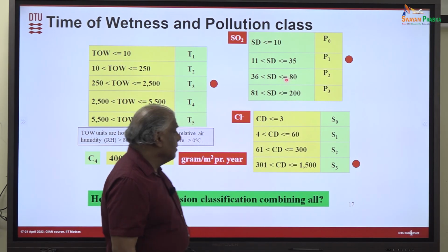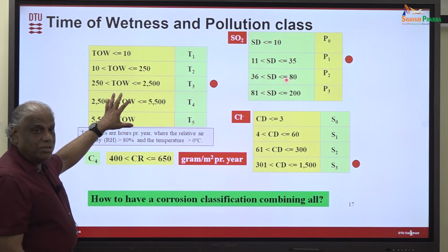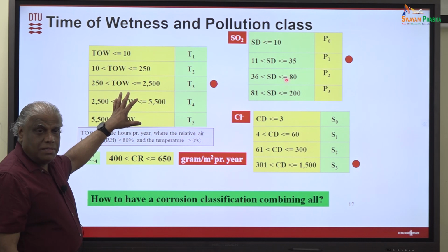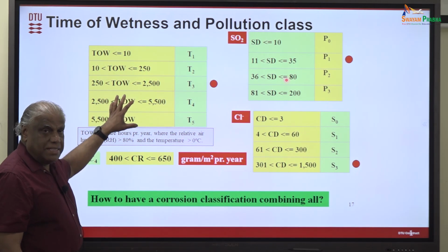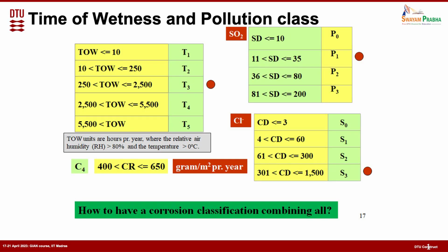That's one part. The second part is that you also need to know how much chance there is for the surface to wet. How can we quantify that? We mentioned that at 100% humidity, which means a saturated humidity level, the surface will have water. Then we mentioned that it's not necessary to go to 100% humidity, because if you have a deliquescent substance, you can get condensation before.